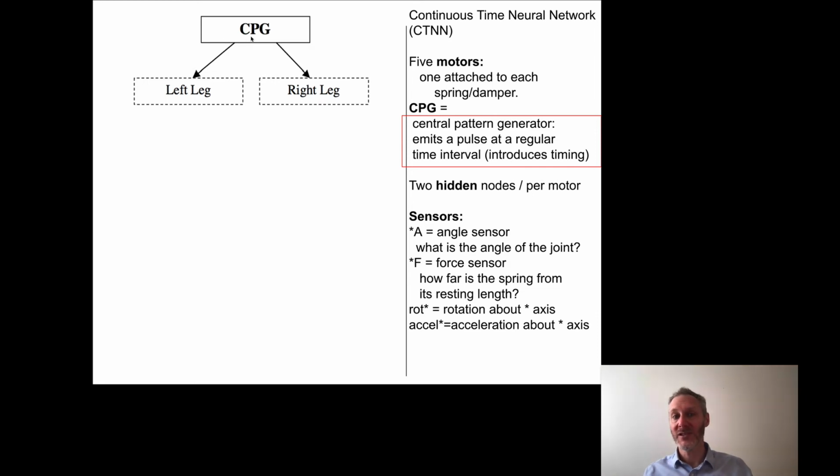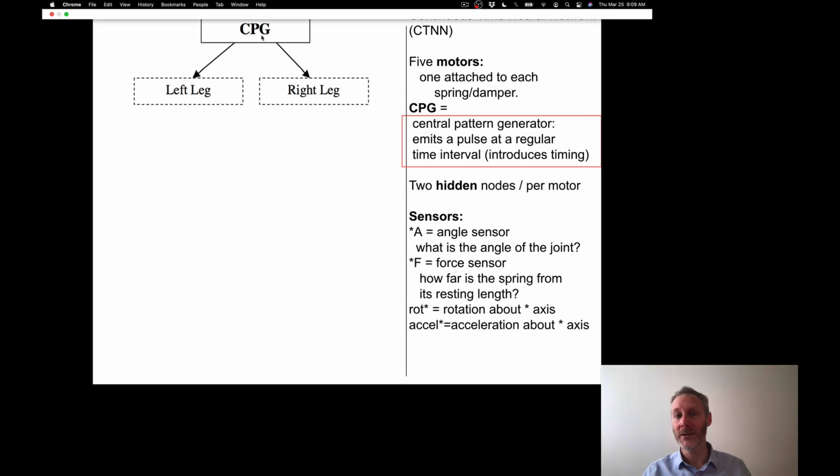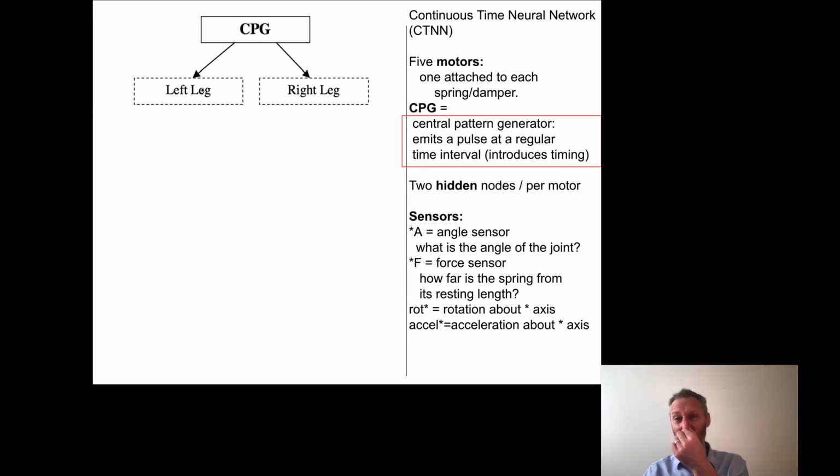So in the very first time step, the CPG sends a non-zero value to the right leg, which causes the right leg to move. The robot starts moving, and 33 time steps later, the right heel strikes the ground, and at that moment, the CPG now sends a non-zero value into the left leg. At 66 time steps, the CPG sends a signal to the right leg, 99 time steps to the left leg, back and forth. So the CPG is sending values into the two legs at a certain frequency that's been determined by how the robot starts moving on the declined plane.